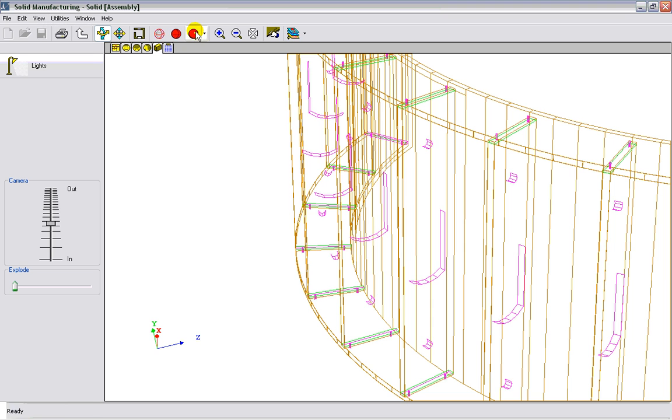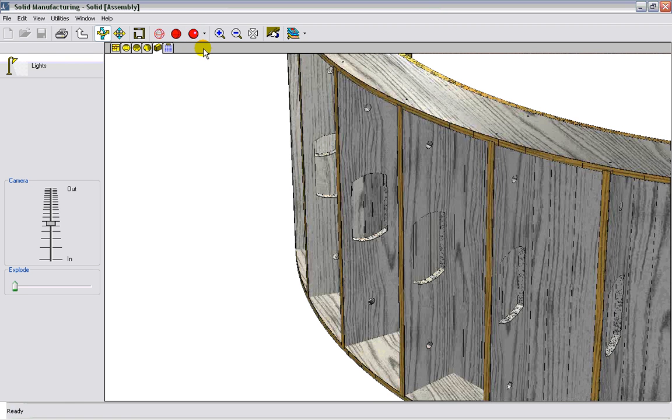If we look closely in high detail, or maximum detail, you will see there are cutouts in all of these partitions and holes at the top and the bottom. These particular cutouts will size themselves automatically depending on the width of your object. So if you create a deeper die wall or a shallower one, these holes will size themselves accordingly. These particular holes, the default is 1 inch.